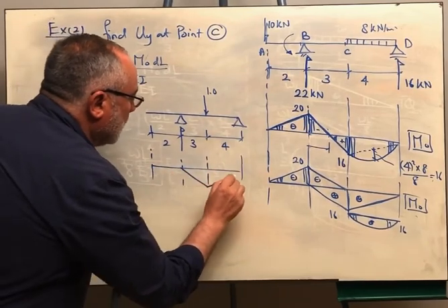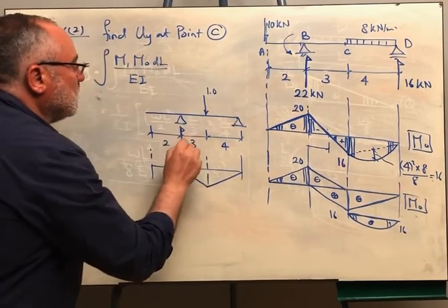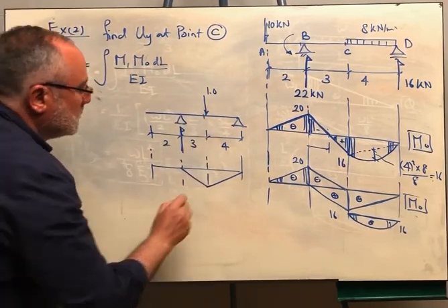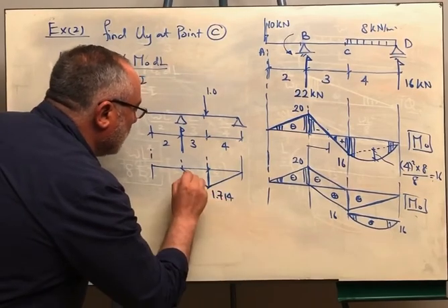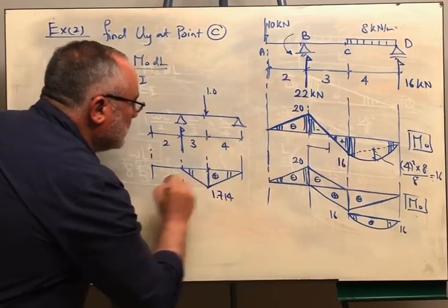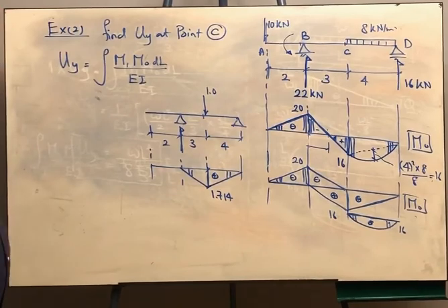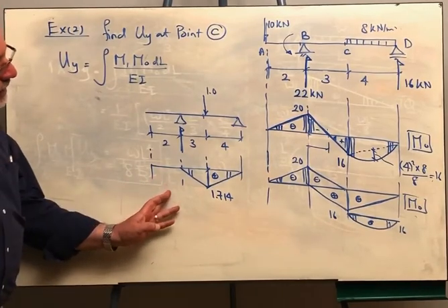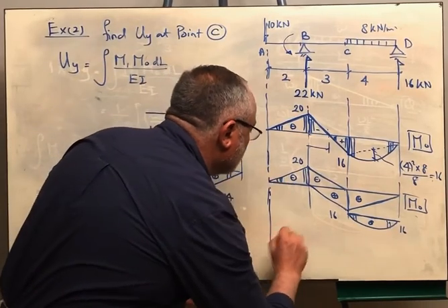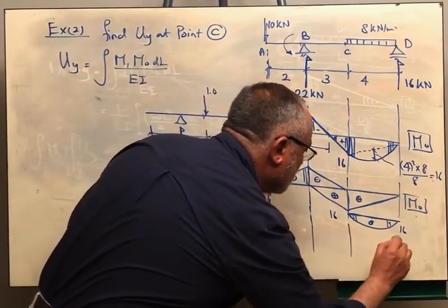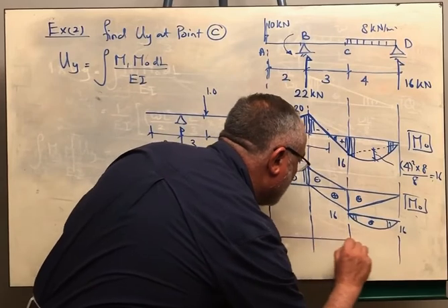The bending moment diagram will look like this. If you get this reaction multiplied by the distance 3, the moment diagram here will be 1.714, and it is positive. So this is M naught. It is better to locate M1 under M naught exactly to perform the integration easily.